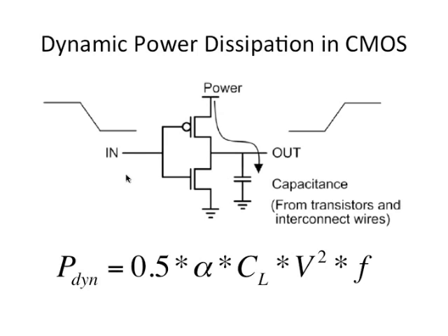So what is the charge finally stored in the capacitor? If the total capacitance at the output is CL, the load capacitance, and it charges to a voltage V, the charge is CL times V. And since the charge is drawn from the battery which has a voltage V, the energy is voltage times charge. So that is CL V square. And the power is the number of times you do it, or the rate of doing it. Since you do it every t seconds, where t is the clock period, F is 1 by t. So CL V square F is the power.